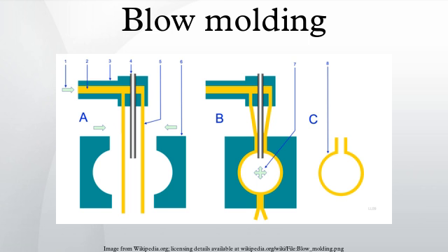The preform and blow mold can have many cavities, typically 3 to 16 depending on the article size and the required output. There are 3 sets of core rods, which allow concurrent preform injection, blow molding and ejection. Advantages: it produces an injection molded neck for accuracy. Disadvantages: only suits small capacity bottles as it is difficult to control the base center during blowing. No increase in barrier strength as the material is not biaxially stretched. Handles can't be incorporated.